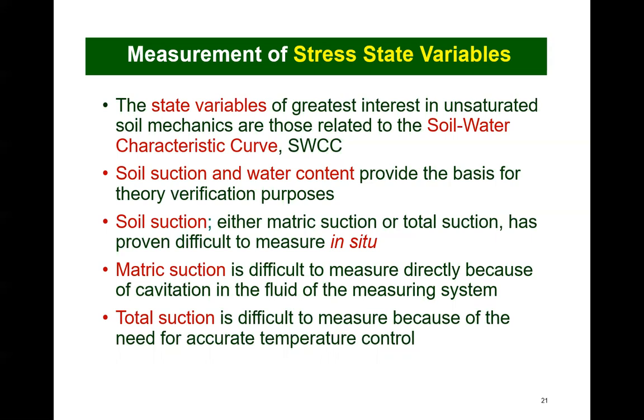Matrix suction is difficult to measure directly because of the problems of cavitation in the fluid that is part of the measuring system. Total suction is also difficult to measure because of the need for accurate temperature control.